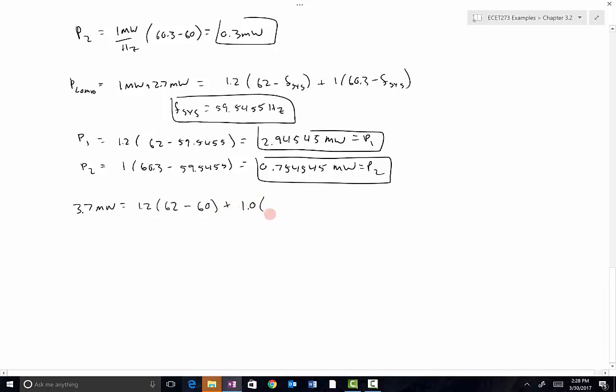And we need to multiply that by its no-load set point. That's what's changing in this problem. So you have to understand generator operation to understand that that's the variable we're solving for. And then we subtract off 60 hertz. So we just need to solve all that for no-load 2, and we get F no-load for Gen 2, where the generator set point needs to be increased to 61.3 hertz, and that will restore total system frequency to 60 hertz for a load of 3.7 megawatts.